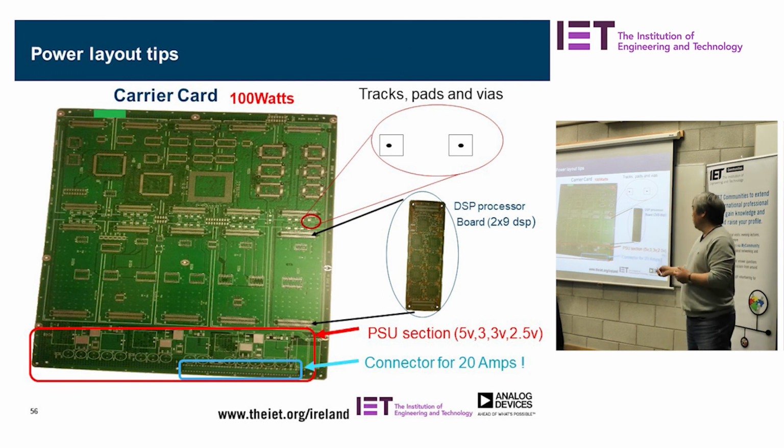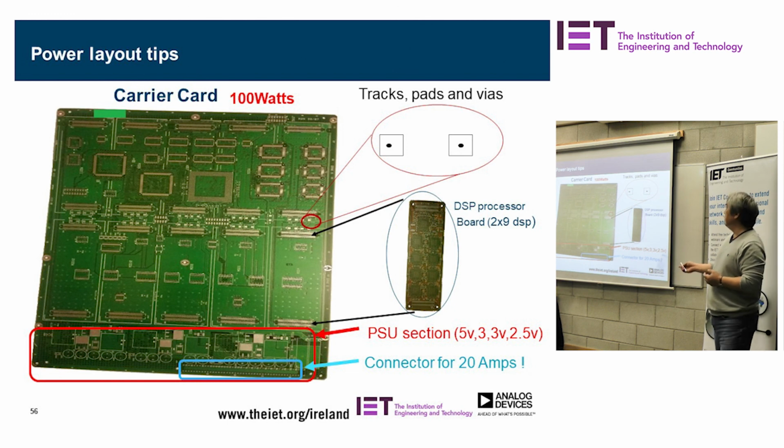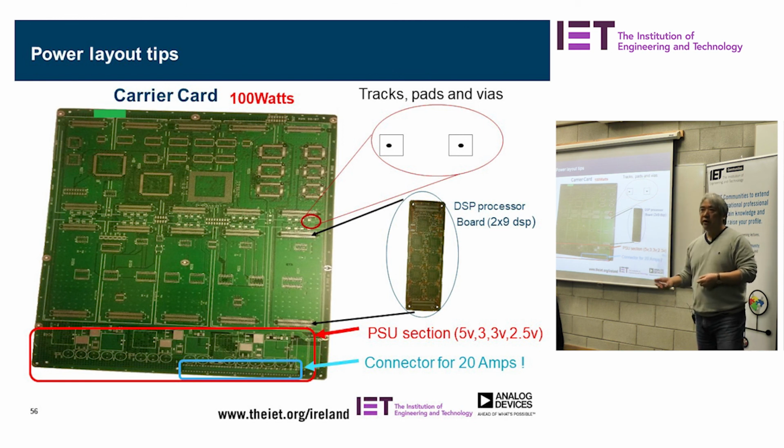Eventually we laid out this board and put enough hooks in place to avoid those issues. The board came back and we managed to test it on day 1, and it worked perfectly. There's no respin, no fault, no burning of tracks. It can handle the power. It shows that, given the complexity, we did this within 1 year. So imagine if you had to respin that board. You need to go back to the drawing board to redesign it and test it, then go back to fabricate the IC again, then the board, and populate again. You'd be set back another year.